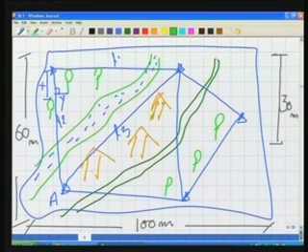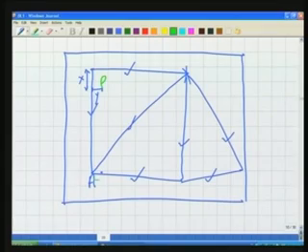For example, for this house, I take the measurements of this house from this line by drawing a perpendicular. I measure this x, I measure this y. By measuring this x and this y, in my map, this is the x and here is the y, and we know there is a house here. So, I have plotted the house also. Now you will start realizing the significance of this control network.